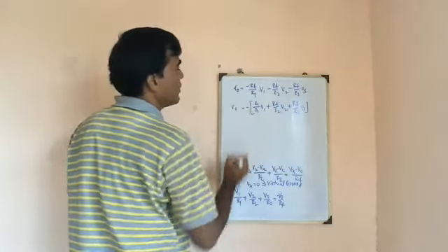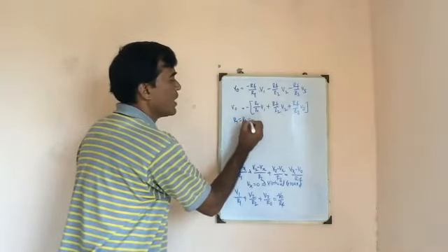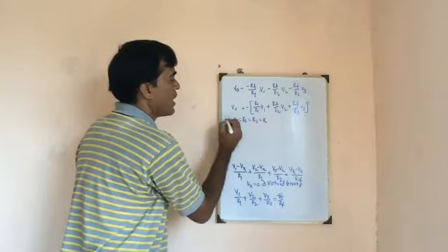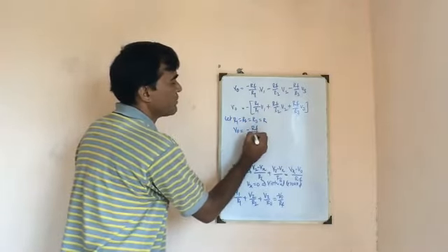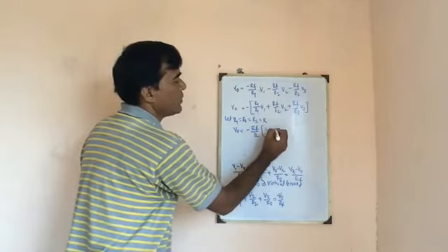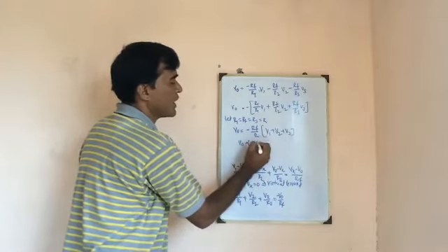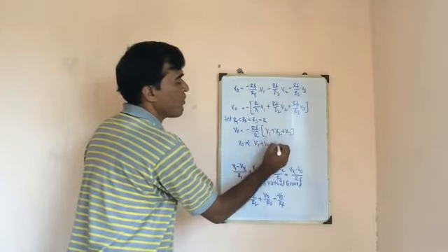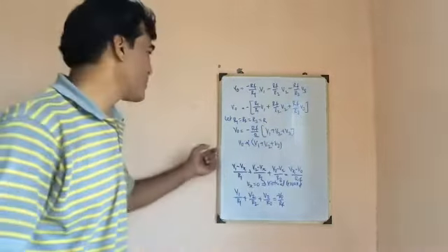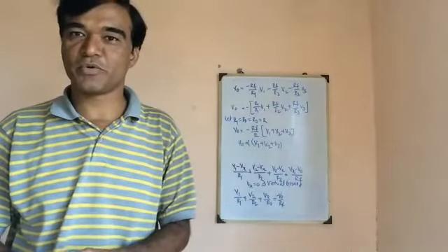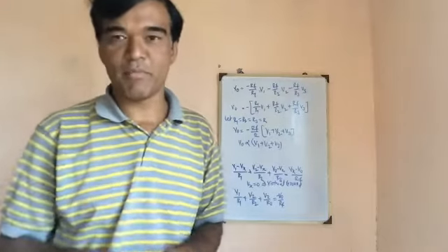Now if I consider R1 equal to R2 equal to R3 equal to R, then the expression becomes V0 equal to minus RF by R times (V1 plus V2 plus V3), which indicates that the output voltage is directly proportional to the sum of the input voltages. That is why this circuit is known as the adder circuit, or the summing amplifier.